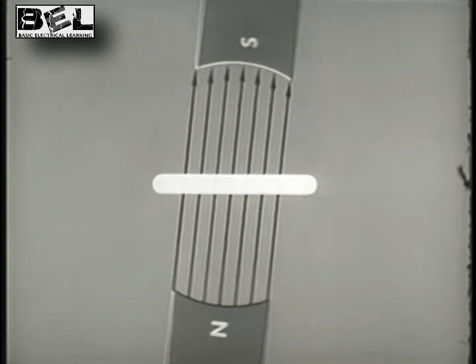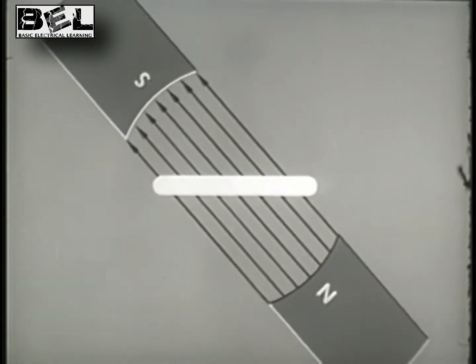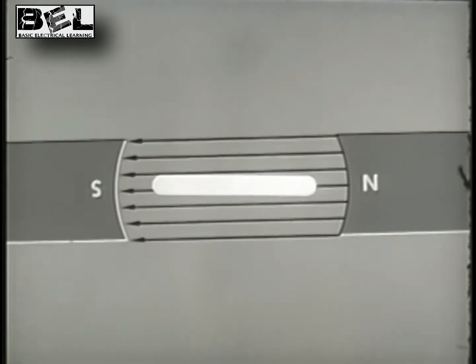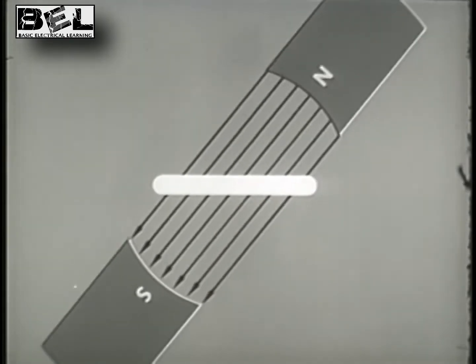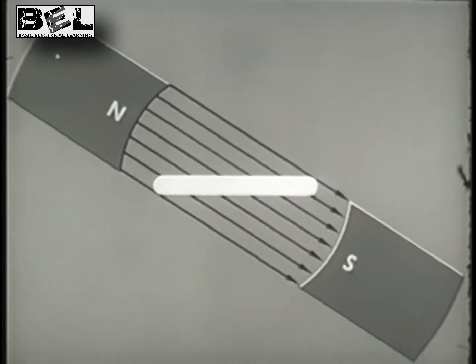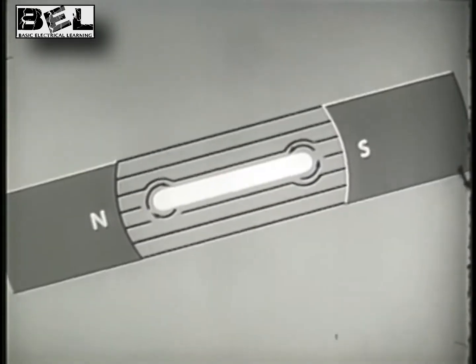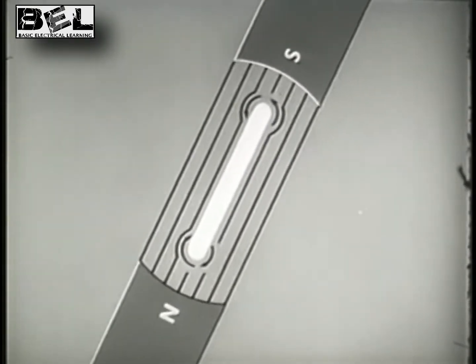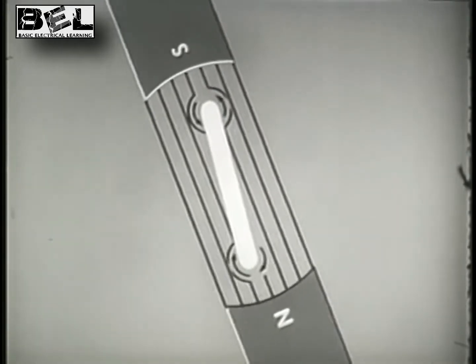This, however, is an impossible situation, for if the rotor stops while the field continues to turn, relative motion will have been re-established. Lines of force are being cut once more. An EMF is generated and the resultant magnetic field will cause the rotor to move again.